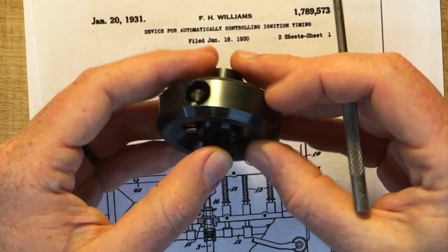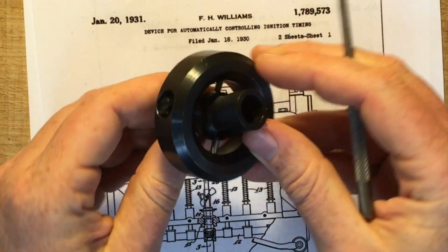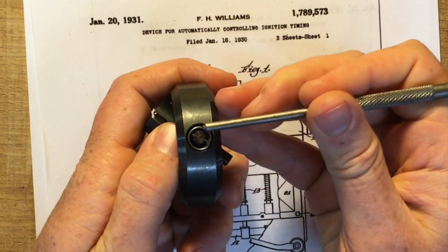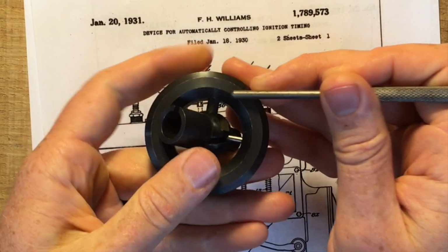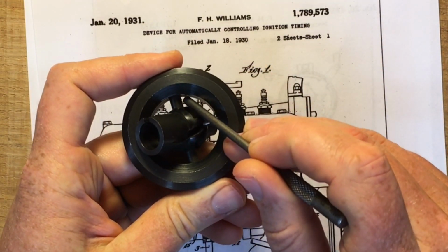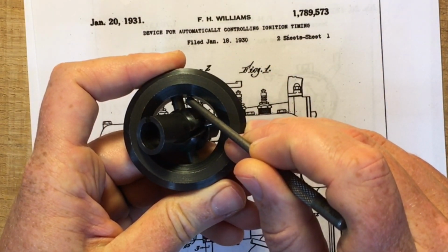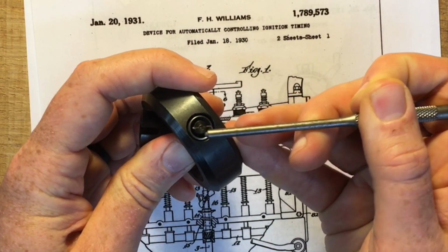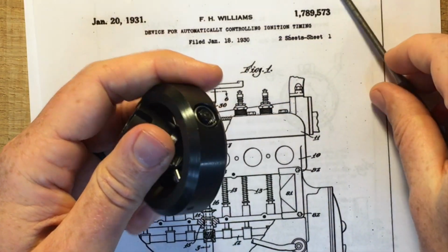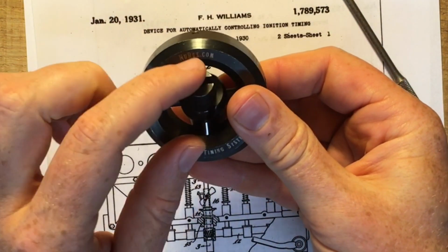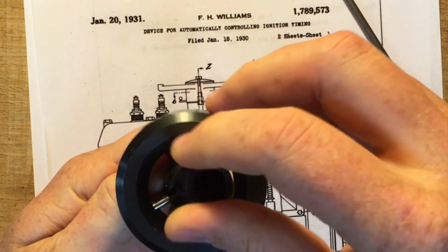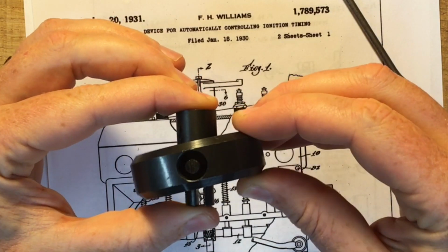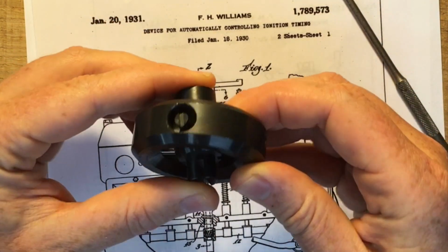And this toroid weight is held in place with a torsion spring. And one end of the spring, probably can't see, is embedded in the weight, and then the other goes through this notch at the end of the gimbal. And as the lower shaft, so this part's the lower shaft, is spun by the drive gear, the weight pivots on the gimbal, which then rotates